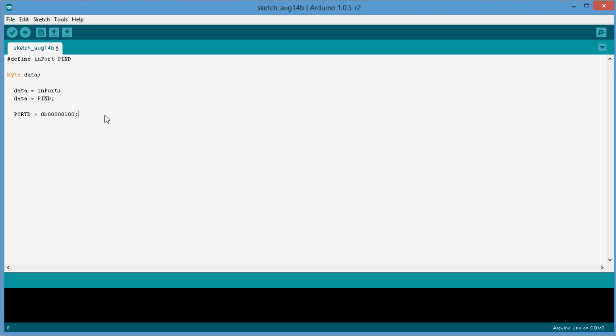Or the thing is that it will affect all of the pins on that port at the same time. And say you've got other stuff being driven by this pin here that you don't want to change. You don't want to make it a 1 or a 0 in this case, but because the software is running, you don't know what the value of this pin should be at the time that you're going to write to just this pin here. There's another way of doing it.